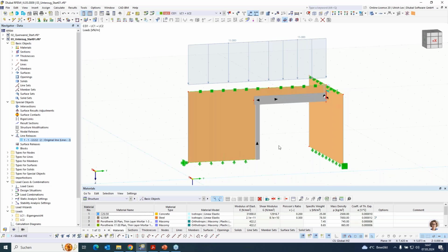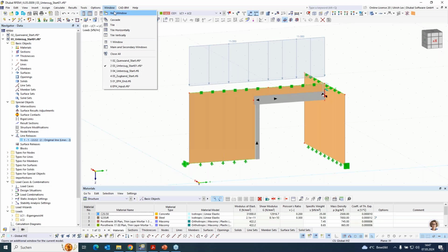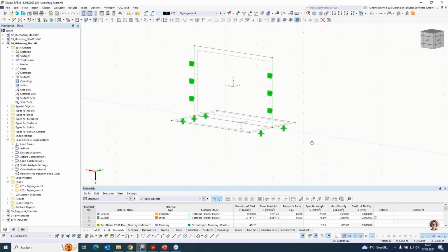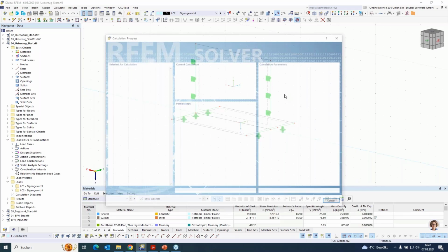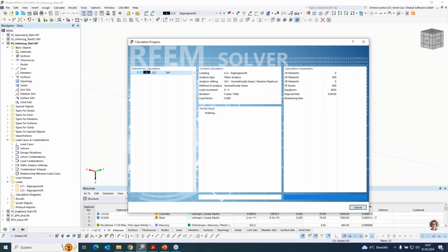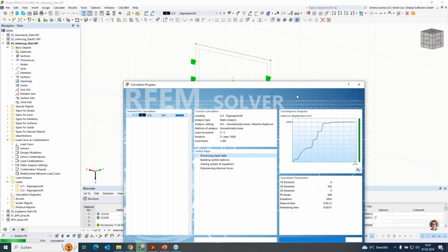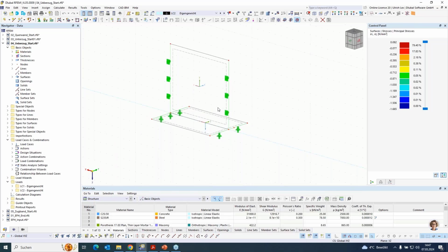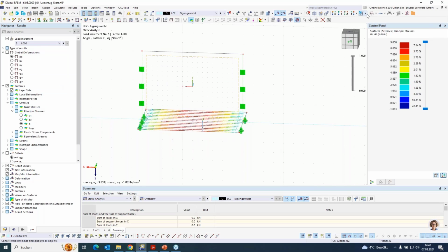Okay, so these were the problems of this example, and now I can take a look at the next example. When you have something like a wall above a concrete slab, where you have no support in the floor below, then when you take a look on the results, you will see that the masonry wall is acting similar to a beam. You will have some forces, like a pressure arc in the masonry wall.